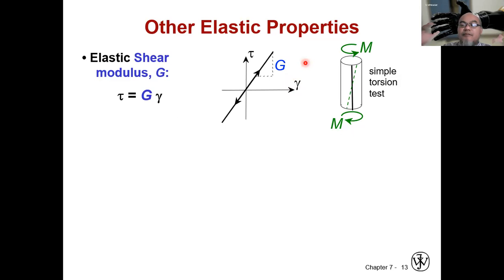When we apply shear, the lower surface is considered fixed, the upper part is shifted, then it forms an angle, represented by this gamma. This is basically similar to strain, but the y-axis, instead of sigma, becomes the shear stress. So in the graph of tau versus gamma, when it is still in the elastic region, the gradient indicates the elastic shear modulus G.